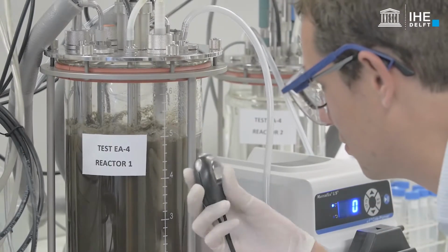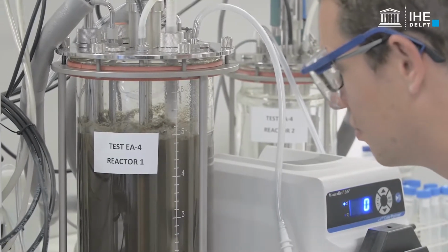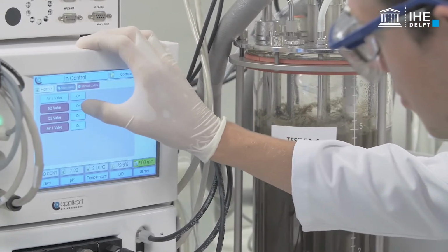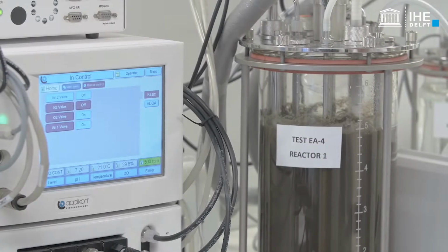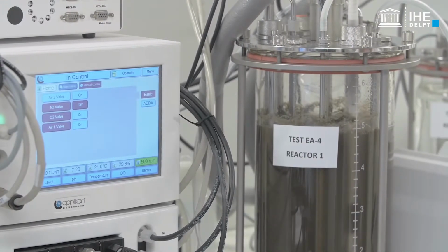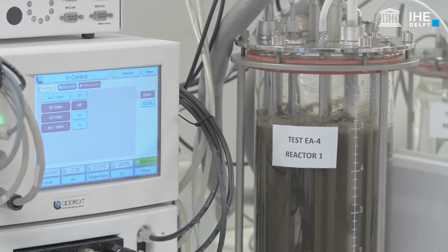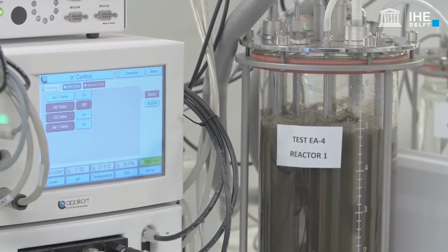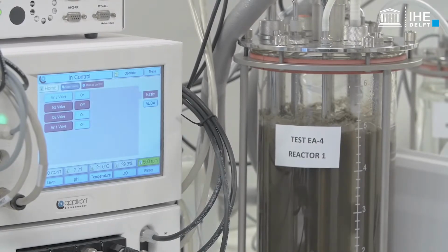Verify the stability of the sludge by assessing the pH, dissolved oxygen concentration and temperature. If stable, start the supply of nitrogen gas for 5 to 10 minutes. This will remove the dissolved oxygen present and create anaerobic conditions. The dissolved oxygen concentration should drop below detection limits to consider that strict anaerobic conditions have been reached.